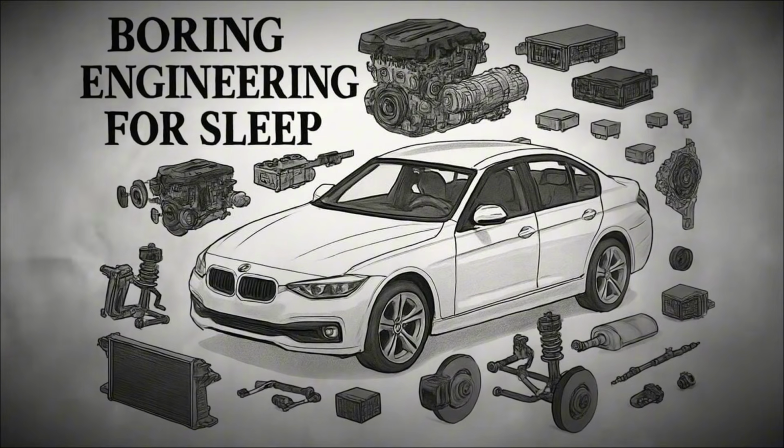When the driver presses the clutch pedal, the release bearing pushes against springs in the pressure plate, lifting it away and releasing the pressure on the clutch disc. This allows the disc to spin freely, disconnecting the engine from the gearbox and enabling the driver to change gears.